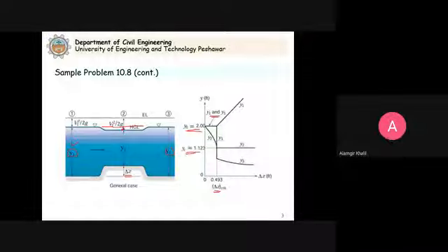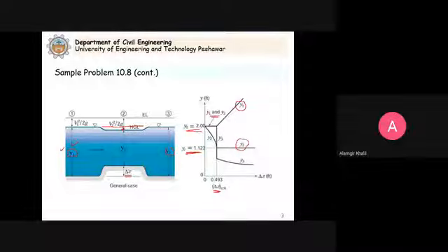Clear? Also, there is a possibility that when we have the critical hump height or greater than that, z increases, and beyond that y1 can increase. It means that the depth at the upstream side can increase. This is what we saw in the previous lecture, and we call this the damming action. Similarly, when we have the critical hump height, the critical depth of water will occur on the hump, and y2 will be critical. That will remain critical as you increase the hump height, because we saw that when the height of the hump is equal to delta z critical or greater, still on the hump there will be the critical depth. Clear?